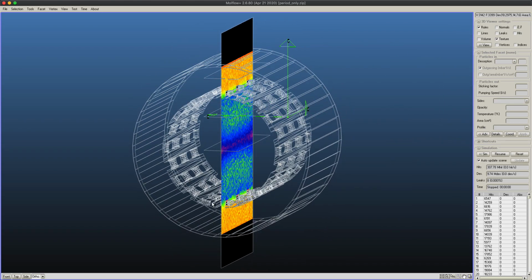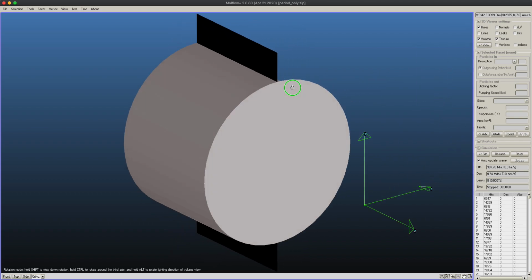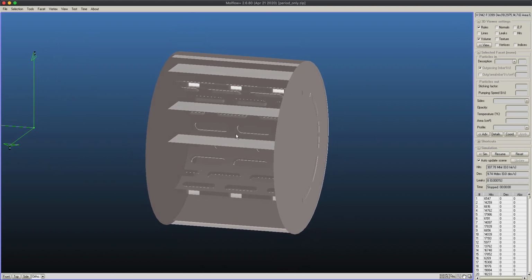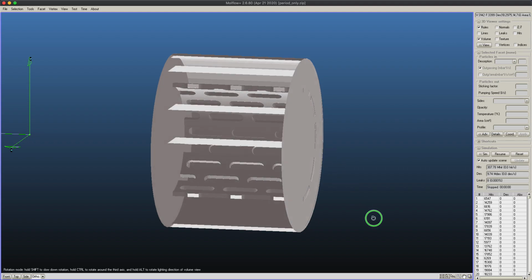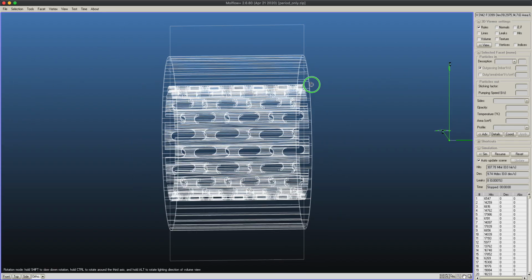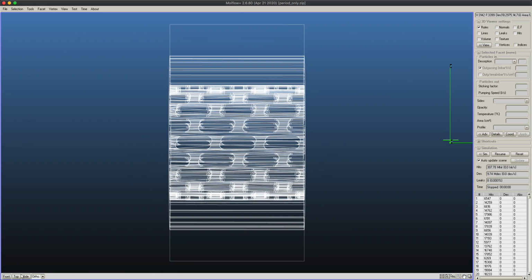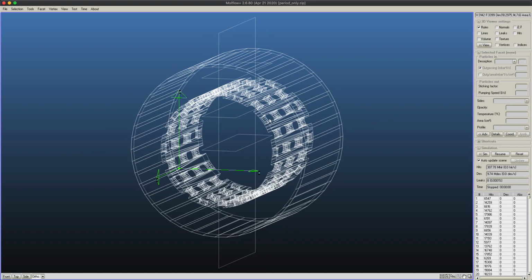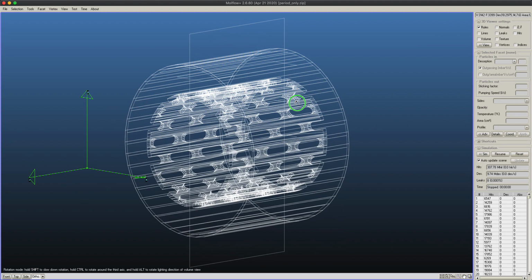Here you can see that we've got an RF liner. It's got some wall thickness. If I turn on the volume view and turn on the texture, you can see that there are some holes. Maybe I will just rotate the lighting so you can see it better. The idea is that since I was modeling exactly one period, if I'm looking from the side, you can see that you've got about 3 holes. Then I could replace this with a single cylinder, but I would like the physics to behave more or less the same as with the full structure.